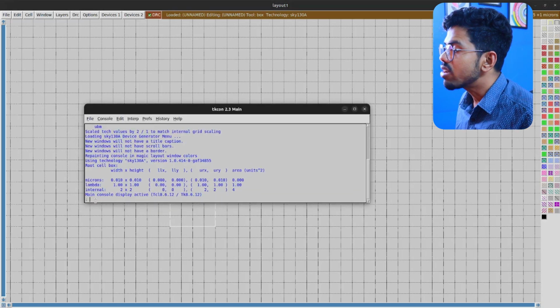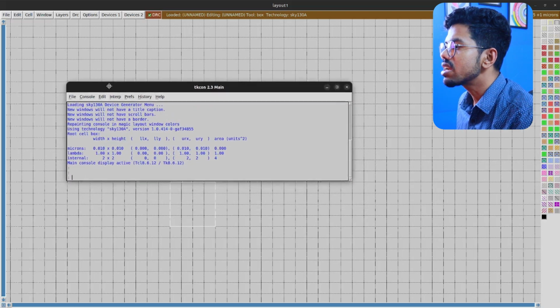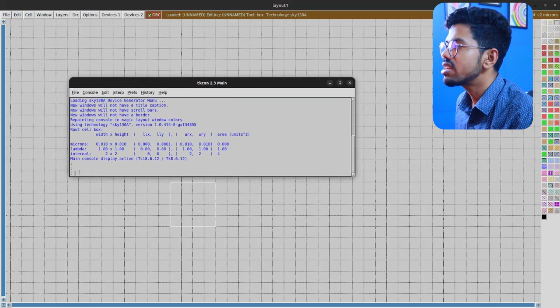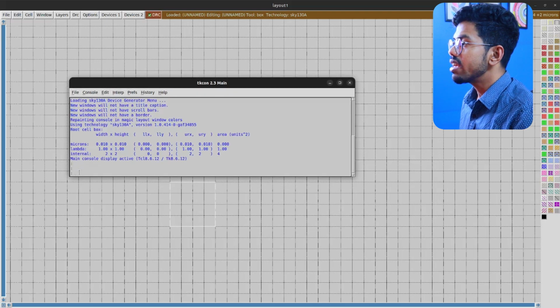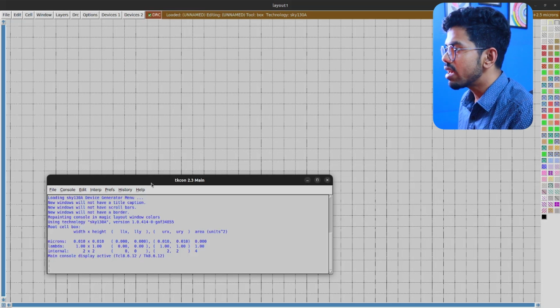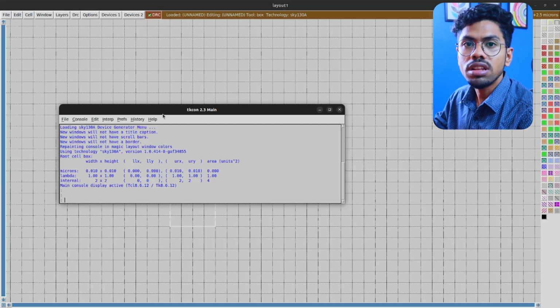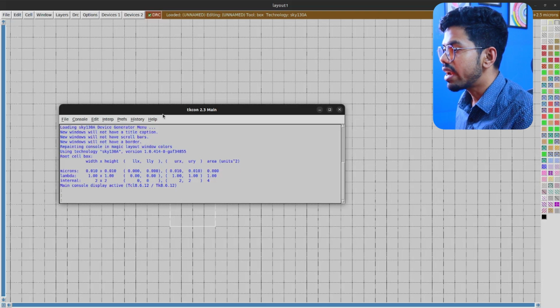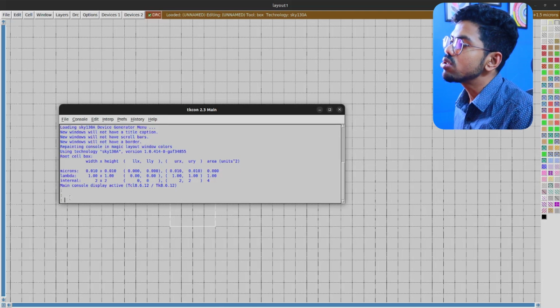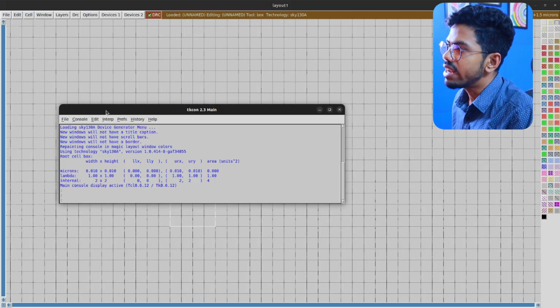Anytime you want to write any command, one way is just bring the window forward, and after bringing it forward just click here, no colon, nothing is needed, type the command. But if this window is not active, probably this window is active, then you don't need to click here and make this window active. You don't need to do that. The simple way is to just press colon. With colon only, like here I press colon, right? This window will become active, but it won't come to the front. It will be active in the background only, and your command will run.